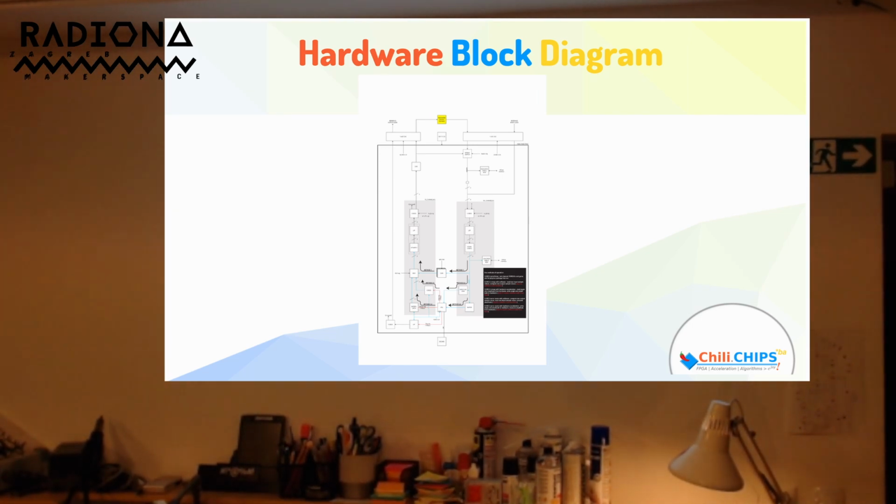Later on, this bypass switch is here just so we can debug better, because if we use this bypass switch, then we bypass the entire path and we can just test out the ADC and the DAC overall. This one is just for high-speed debugging because the input is going at 65 megasamples per second. Here we have these 5 modes or 5 buses.